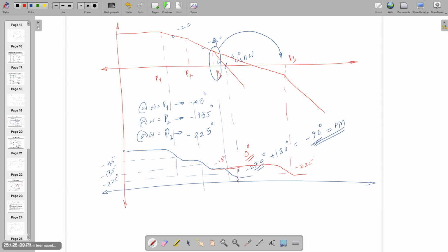Now this is also not satisfactory. We need to make sure that the system is stable when the phase margin is greater than 45 degrees. This is only possible when we take this P2 also outside. If you keep it exactly on UGBW, you are going to see a phase margin equal to 45 degrees.